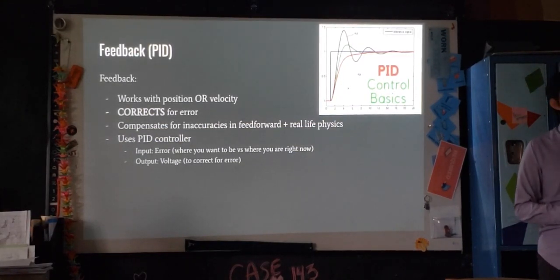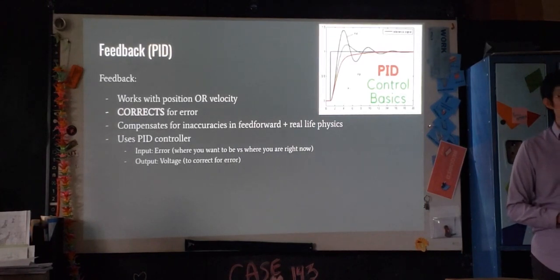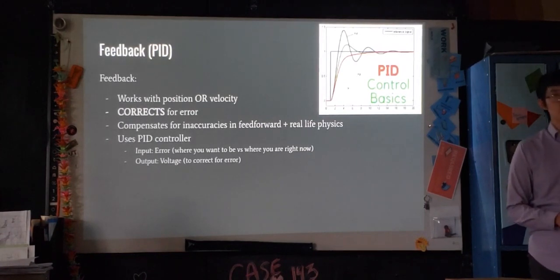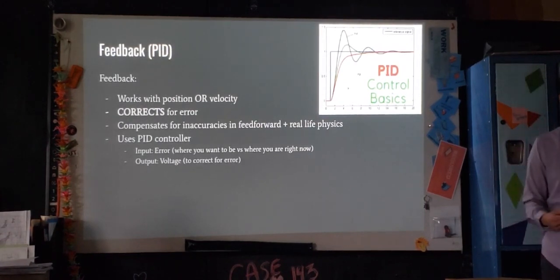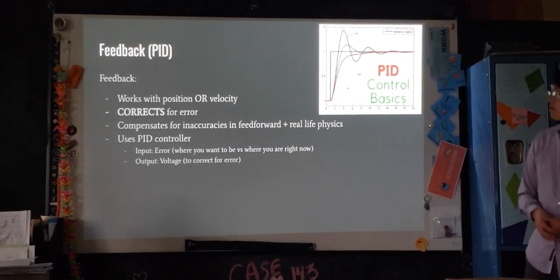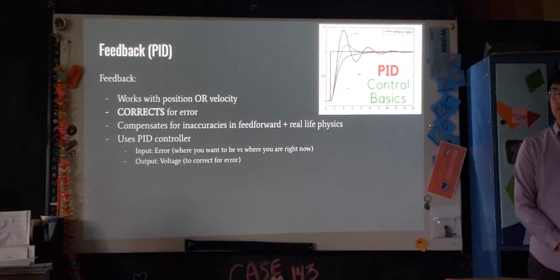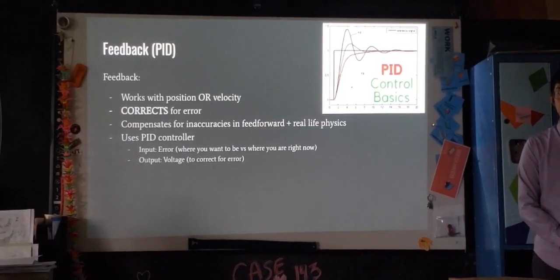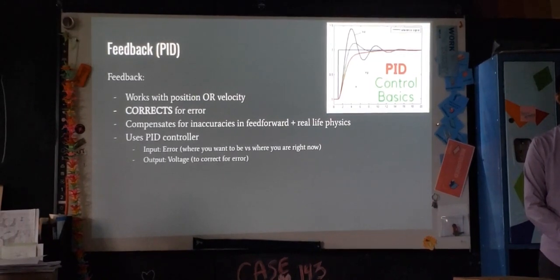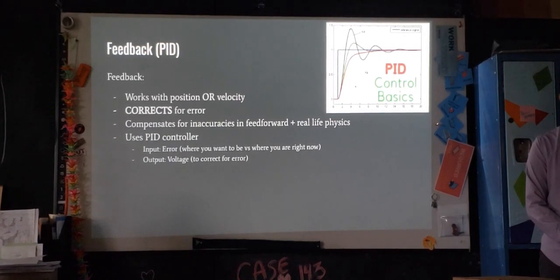If you replace a motor, each of those events probably causes recalculation. Absolutely, because something about your robot changed, so you recharacterize to get the new behavior of the robot. And that's the big downside of feed forward, right? It's at best just a single point in the operating space. And if you change anything about the robot physically, if you add any weight, it immediately has an effect on how good the values actually are.